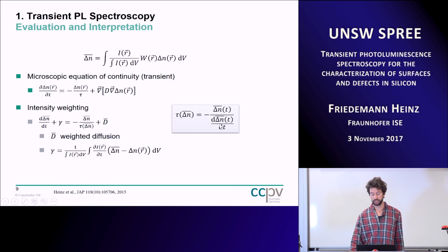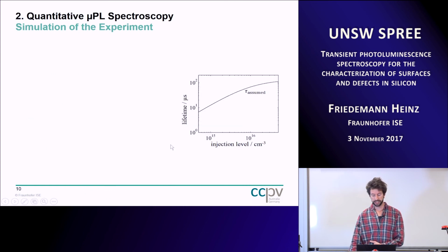And compared to the formula to calculate lifetime, we see the difference here. We have the recombination term. This is simply this one resolved towards tau equals this, but then the diffusion and this term are missing. But now this cannot be simply solved towards the charge carrier density, because this term itself depends on charge carrier density. But it can be solved iteratively.